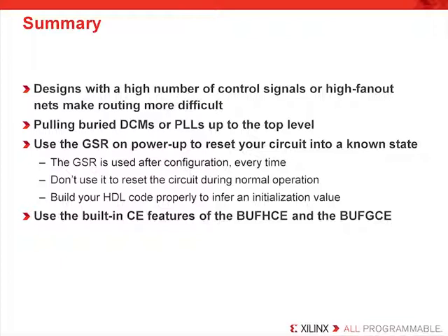You should also use the GSR on power-up to reset your circuit into a known state. And to define that known state, you have to code in your HDL the appropriate HDL code for behavioral simulation to start up at a 0. Now, the GSR is used after configuration every time. That's the standard part of the configuration process, so it's already being executed. So it's probably a good idea to take advantage of it and save you from routing an additional global reset net throughout the FPGA. This would actually, in effect, use general interconnect and perhaps prevent the tools from routing your design to completion or meeting your timing objectives.